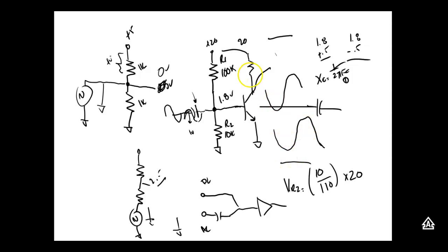But it's going to be riding on DC. Transistor amplifiers are amplifying DC. We make it appear they're amplifying AC by coupling, right? So on this one, I'm using a capacitor to let the AC signal in, keep the DC bias there. But I want to do the same thing over here, because this is going to be riding on DC too. So we'll put another capacitor over here, which will block this voltage right here, and allow us to get AC out.